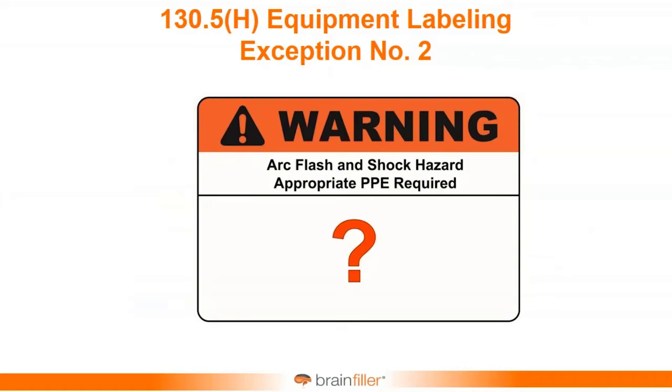And I know this flies in the face of what we're used to. But what you can do is instead reference the department, the group, the person that has the report, the arc flash study. And so what you do is you look at, okay, what configuration are we in right now? Let's look at the report. Let's see what configuration we're in. Let's see what the information is for that configuration. And let's dress and protect ourselves based on the mode that we're actually operating under right now.